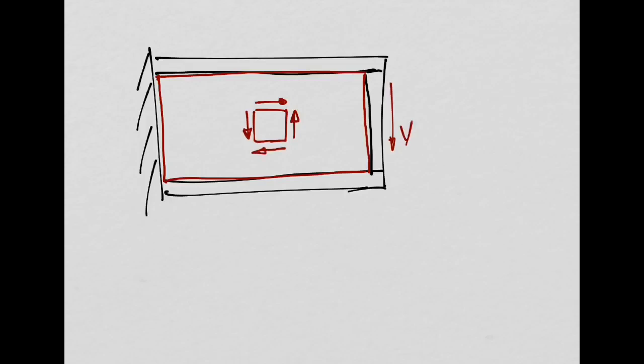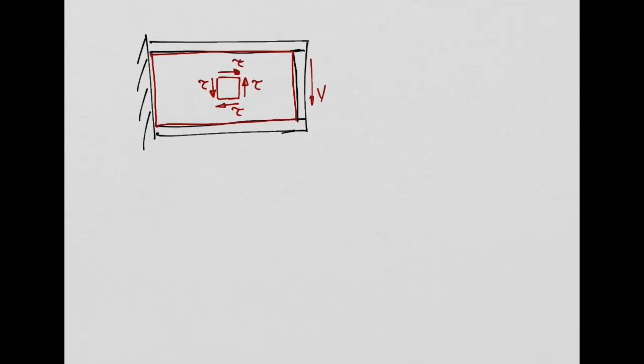Plane stress analysis, yeah? If you have an element only under pure shear, right? You have something like this. So this is the shear stress, tau, yeah? Okay? You remember this, right? So this is what is happening on the web. You have this kind of stress state on the web.